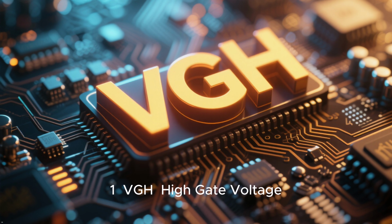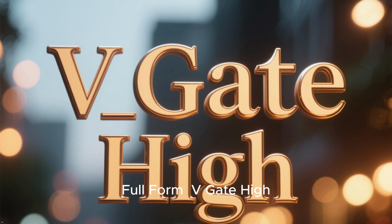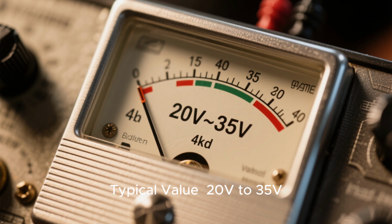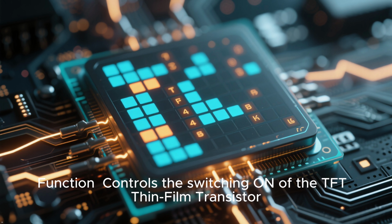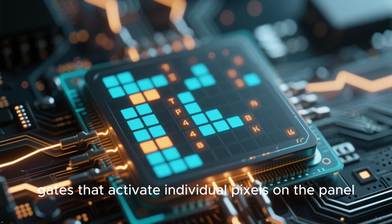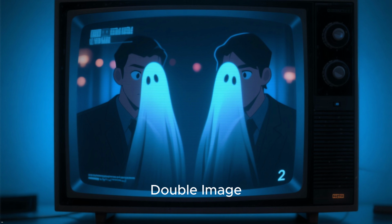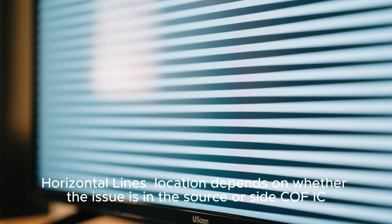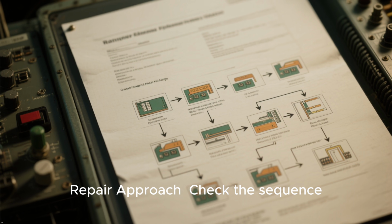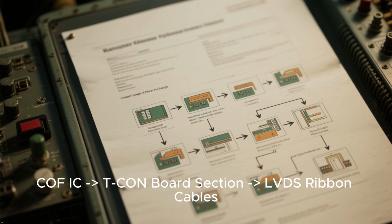1. VGH, high gate voltage. Full form, V underscore gate high. Typical value, 20 volts to 35 volts. Function: controls the switching on of the TFT thin film transistor gates that activate individual pixels on the panel. Symptoms of missing: no display, double image, horizontal lines. Location depends on whether the issue is in the source or side COF. Repair approach: check the sequence, the TCON board section, LVDS, ribbon cables.